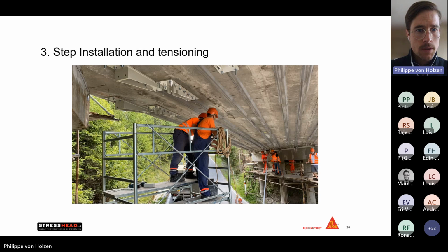Now we can see during the tensioning process itself, we make safety steps. We don't apply the full force at once. We go in those steps and review that we don't have any corrosion in the system itself. We as well review the anchor parts and check that we don't create any new cracks by applying this additional post-tensioning force or introducing the force to the structure.